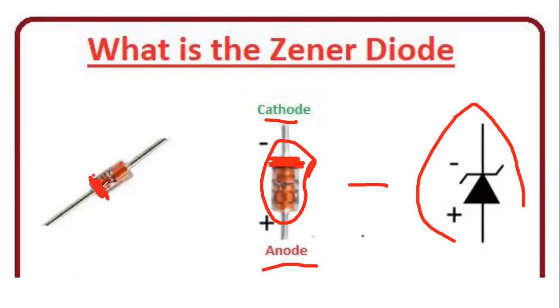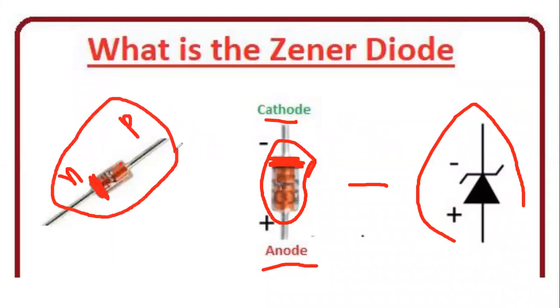That when it is a strip, a strip of black line or white line, the strip is also always N, and the other part is P. Okay, so this is the technique to identify the diode in practical life.